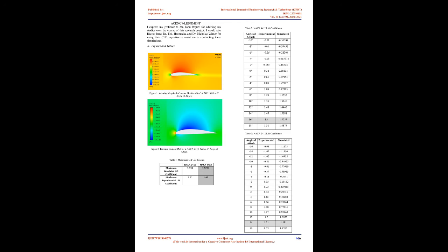Another effective method to validate the data is to compare the obtained numerical lift coefficients with the velocity magnitude contour plot during a stall. Valid data will reflect that the angle of attack providing a maximum lift coefficient corresponds to the stall angle. Further, at the stall angle, the air begins to separate from the wing. Table 2 and Figure 8 demonstrate consistency with the known properties of stalls in physical reality. The pressure and velocity contour plots for the NACA 2412 are in the appendix and also obey these properties.